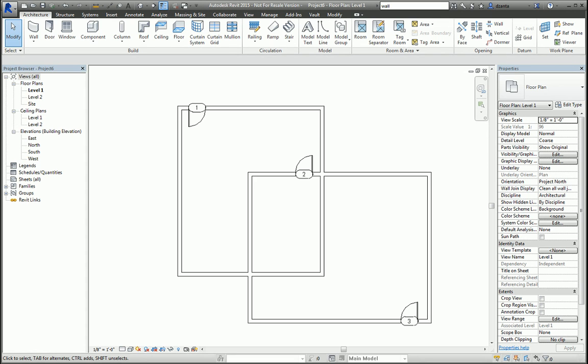In today's screencast, we'll be looking at the actual Revit component command. Here I am in a Revit project. If I look at the Architecture tab of the ribbon, Build panel, I have the component command. If I hit the little black arrow next to it, I can get a menu drop-down where I can either place a component or model one in place.